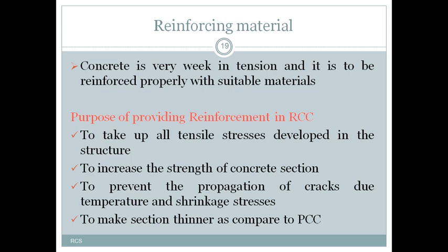And as PCC is very strong in compression, if you prepare any concrete section with PCC, we have to make a larger section for withstanding the load. Now in that PCC we are providing reinforcement in the tension zone. Now our section will become stronger in compression and stronger in tension, so that we can reduce the section. We can reduce the section of the RC member, so that by providing reinforcement in the section, we can make a thinner section compared to the plain cement concrete.